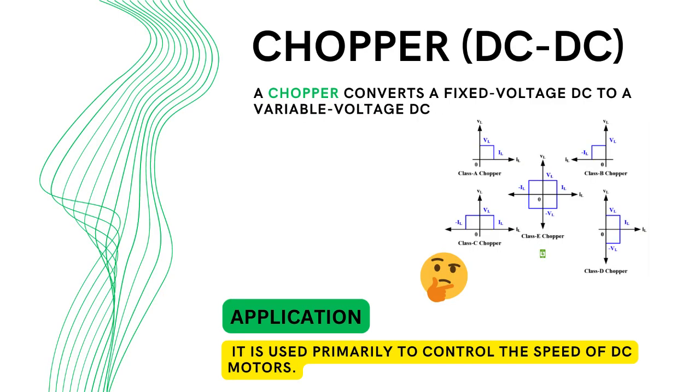Choppers or DC to DC converters. A chopper converts a fixed voltage DC to a variable voltage DC. There are 5 types of choppers: Type A, Type B, Type C, Type D, and Type E. It depends on the polarity of the voltage and current as shown here. Application: it is primarily used to control the speed of DC motors.